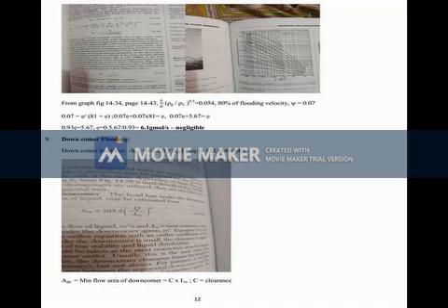Then phi, what is phi? Phi is e raised to minus 12.55 into Ks raised to 0.91. What you don't know is Ks. Ks is equal to UA into (rho G by rho L minus rho G) raised to 0.5. All these equations are available in Perry.